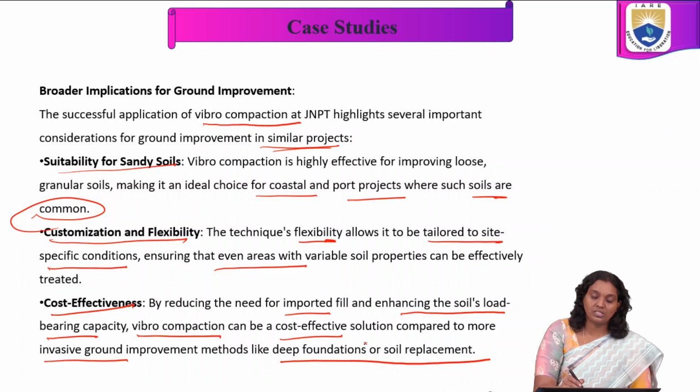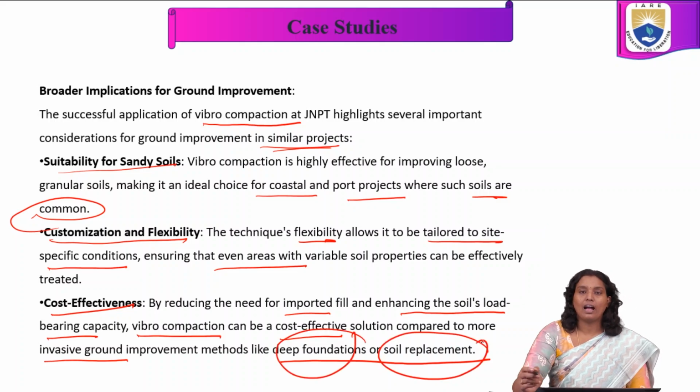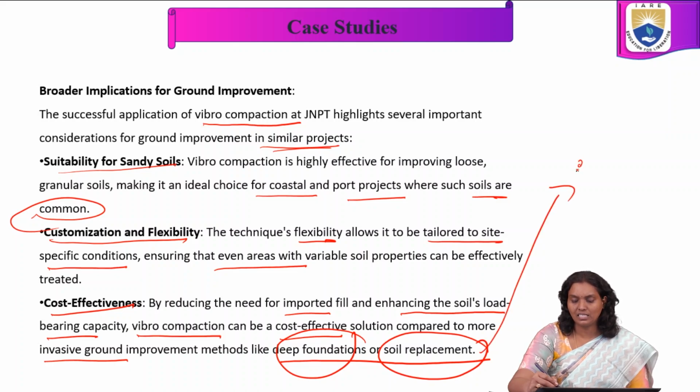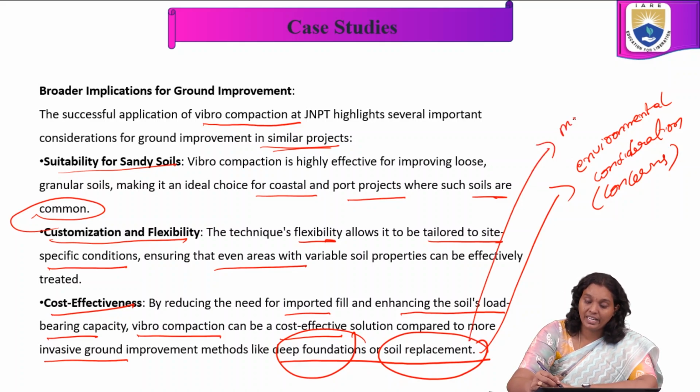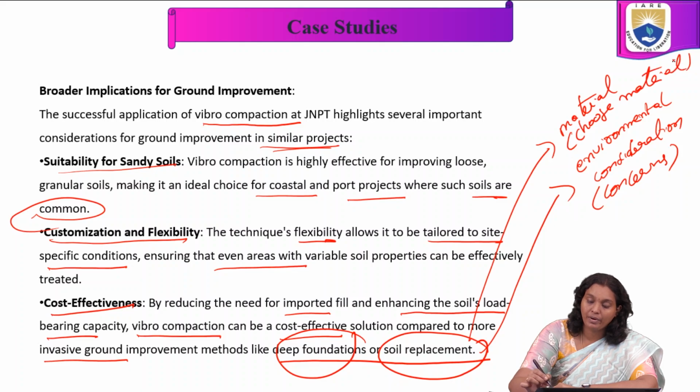So when we choose deep foundations or soil replacement, more environmental concerns and considerations are required, and it also requires material, and choosing the material is also an important parameter that needs more attention compared to vibro compaction.